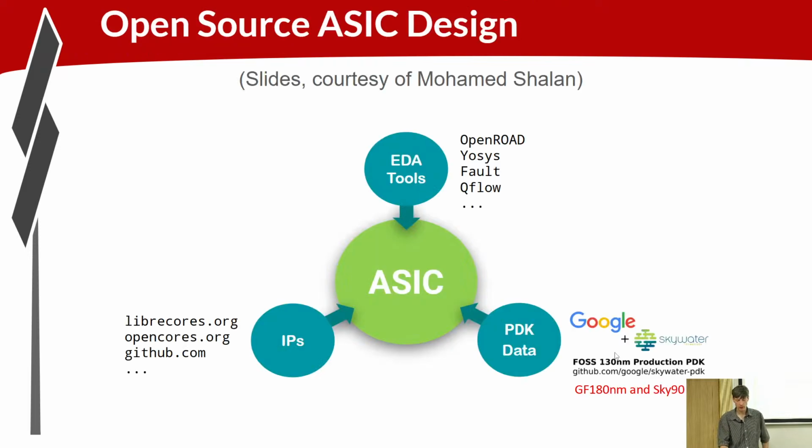And then, our flow, we're looking at Skywater. Google was a part of this for a while. I think they've dropped out at this point. But Skywater is our 130 nanometer fab where your designs will be shipped. Global Foundries was also in the picture for a little bit with their 180 nanometer technology. This slide says Sky 90 is coming soon. This slide is kind of old. I haven't seen Sky 90 yet. I'm not sure what happened there or if that's still coming.